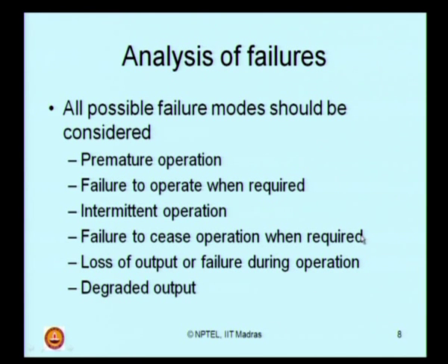Now you have got a sensor that is supposed to give me an output, but the output is not coming from the sensor: loss of output during operation. Or you may get an output, but it is not of the desired quality, so degraded output. All these are different views of failure modes, different possible failure modes which must be considered in your FMEA.